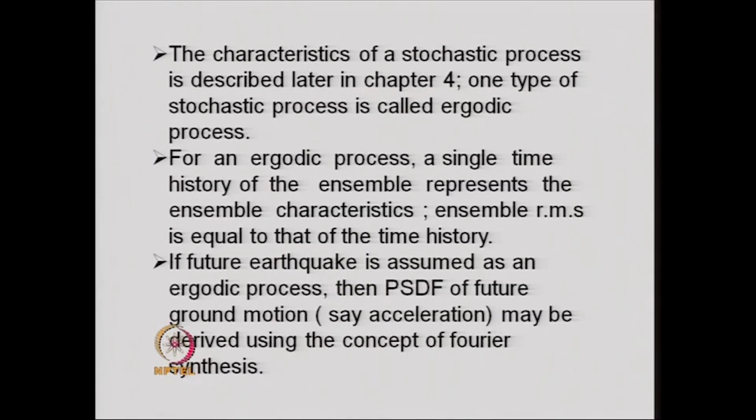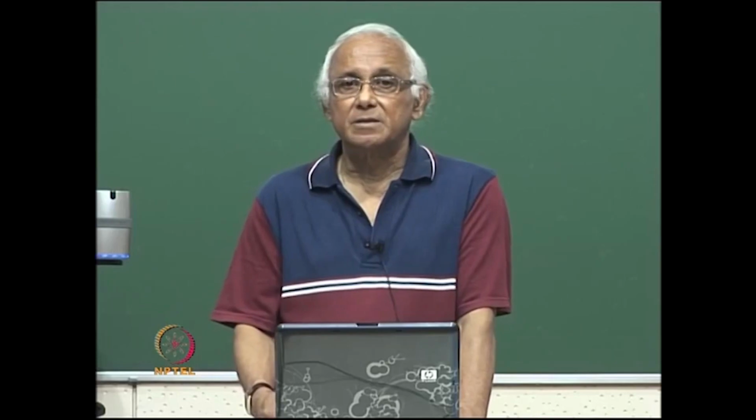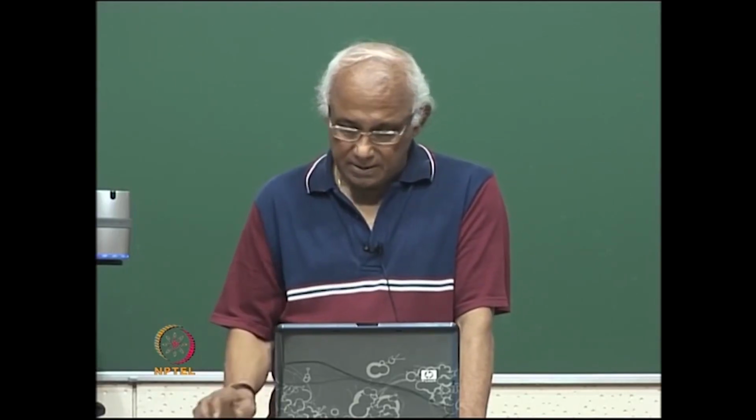Now, this can be easily done with the help of the Fourier series analysis that we discussed before. So, at this stage the assumption of ergodicity helps us in defining the power spectral density function of ground motion with the help of a single time history and using the Fourier series analysis. Now, the rigorous definition of the power spectral density function from the ensemble of time histories will be discussed later.